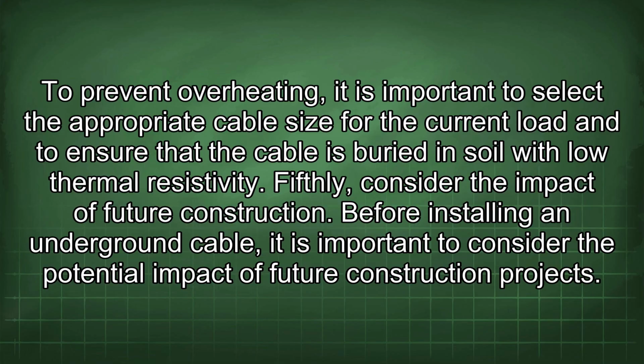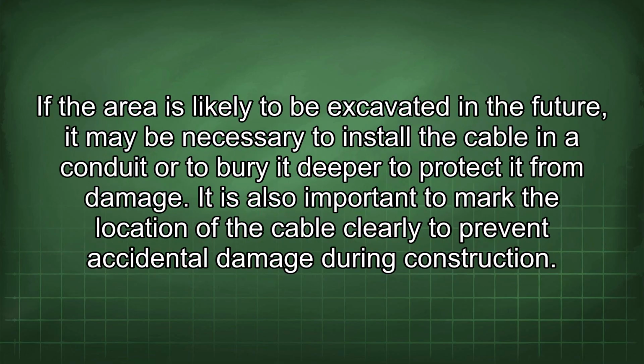Fifthly, consider the impact of future construction. Before installing an underground cable, it is important to consider the potential impact of future construction projects. If the area is likely to be excavated in the future, it may be necessary to install the cable in a conduit or to bury it deeper to protect it from damage. It is also important to mark the location of the cable clearly to prevent accidental damage during construction.